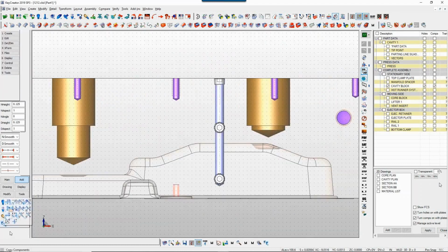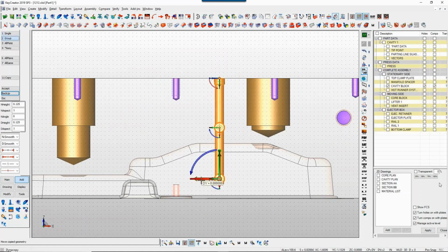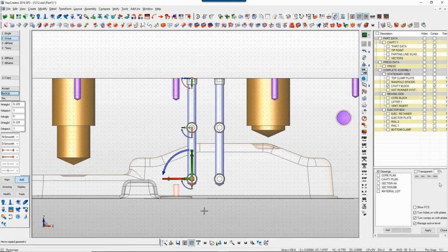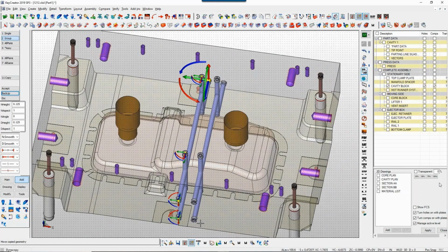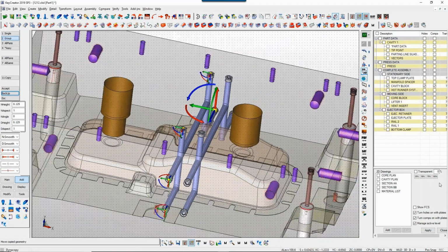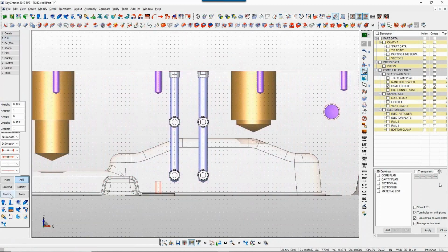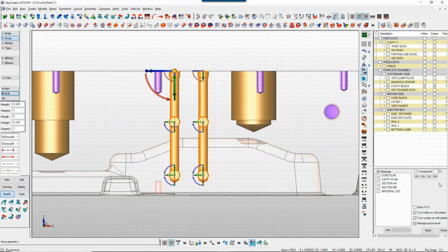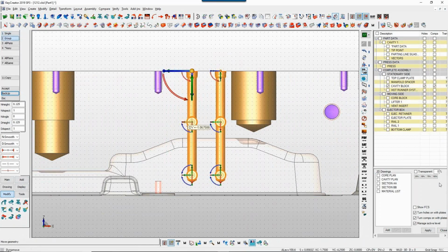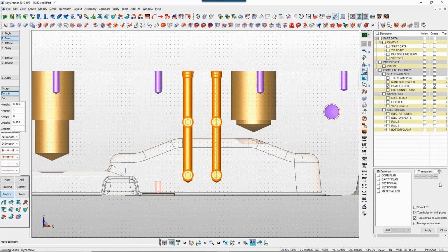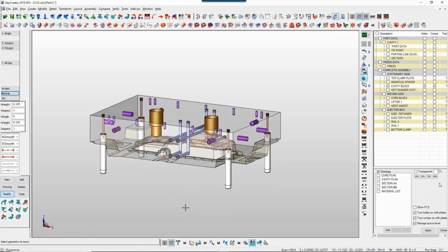Of course, from there, I can copy this as well, right? So I can window around this entire circuit, and I can copy it over however much I want, right? So in this case, I'm just going to copy it over just by eye. The 1 3/4 inch, that looks pretty good, right? Maybe I'll go, yeah, that's good. Okay, and then, you know, same thing. What if I want to take both those circuits and move them over? Maybe go a little closer to the drop or something like that. I can window around both of them, and I can drag them both over, right? So there's a lot of flexibility on moving everything around however you want. And because I've got my snap, it's keeping everything nice nominal numbers, just kind of automatically, right?